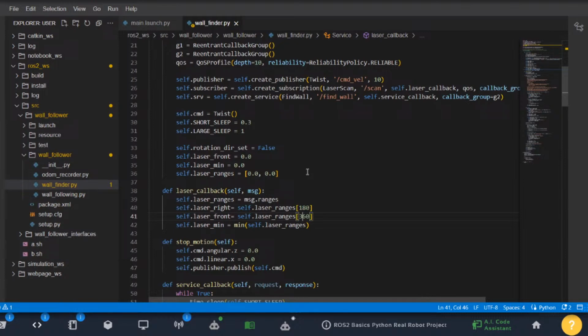Sometimes this is frustrating because every laser sensor is different, or reports its position differently. You don't know if the 0 element is the front, the right, the left, or the back. So you have to do a little bit of hacking by moving the robot around, because you don't have access to the full specification. With a little bit of tampering, at the end you will get what number of the range belongs to each point of the robot. Then we will get the minimum.